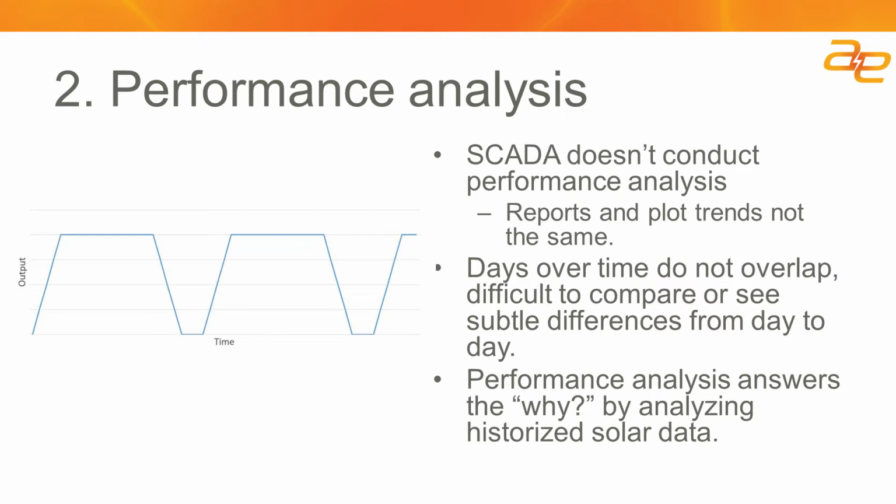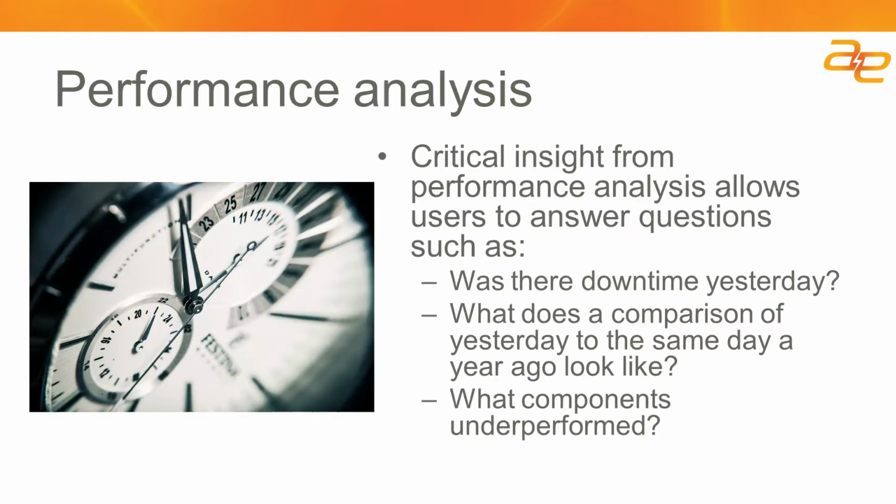It's a little hard to find equivalent days, but again, the time of the year is important, but much more important is the ambient temperature and the amount of irradiance the site gets over the course of a day. So some of the critical insights: you might see over the course of a day that an inverter's output was good, and then it went to 0 for a period of time, and then it went back up.